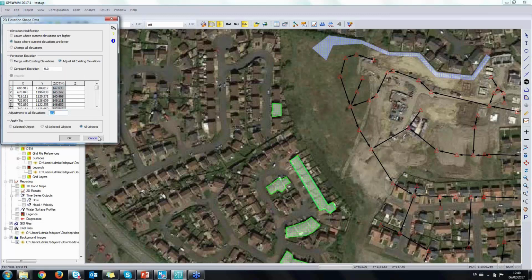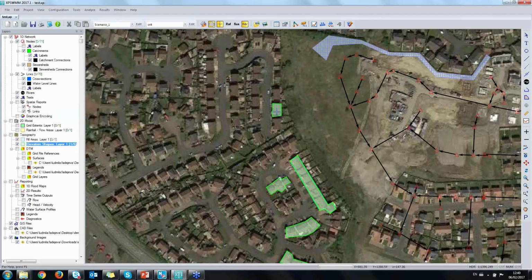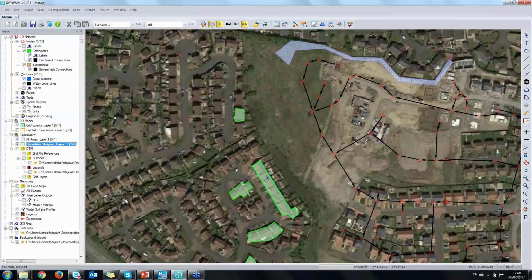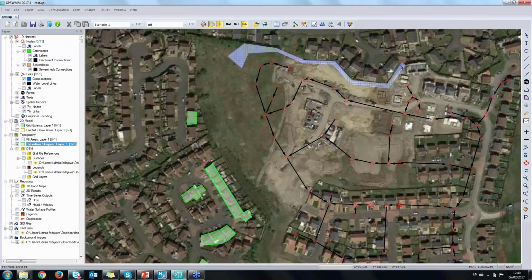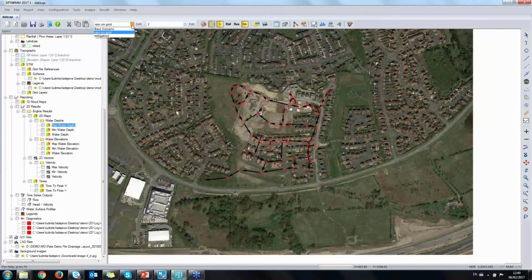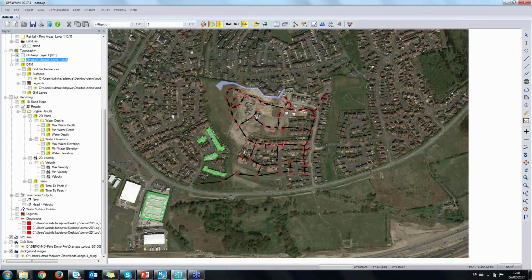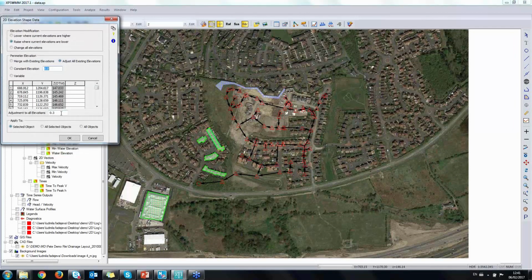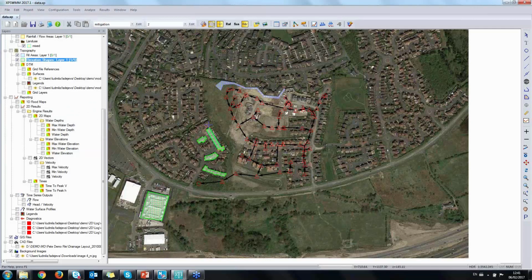In my main model, I will have every single item which is in green higher by 200 millimeters than my DTM. And this channel, I will give it a level in my main model and it will be able to collect some of the water. So if I go back and switch to my mitigation scenario, you can see that these objects come in. So all my items are higher. So it should be 0.2. We played a bit with Peter before, but it is 200 millimeters higher. And I have a collection channel to protect these properties.